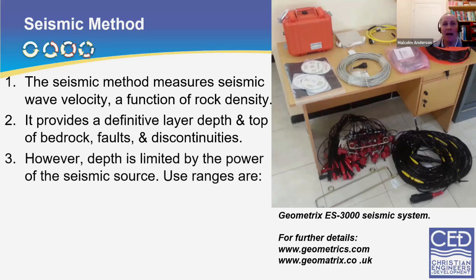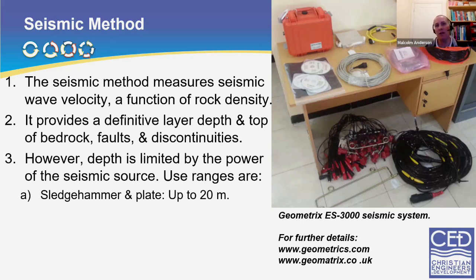However, depth is limited by the power of the seismic source, and this is where the real issue is for our purposes. If you use a sledgehammer and plate, which is obviously low cost, that's exactly what we would want to use, we can only reach 20 meters. Alternatively, we can use a trailer with a weight drop on it, and that will get us down to 1 kilometer if you're in ideal conditions, but certainly well past the depth that you want for a borehole. The problem is that you can't put a trailer and a really heavy weight in your baggage on the plane, so it's not something that you can easily transport to most of the locations we go to, and in general, it's not available locally.